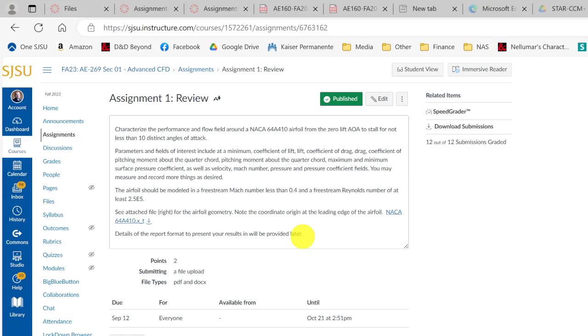And then I had a question about the second one. For my heatsink, the spacing between the fins is 1 millimeter. So it was heating up really a lot. How thick were the fins? 5 millimeters. Oh, okay, so you had a gap that was substantially smaller than the order of magnitude of your fin thickness.